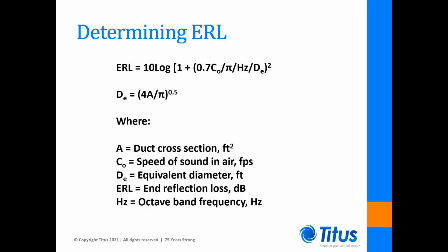These were to be added to each reported octave band up to a maximum increase of 14 decibels. Units with smaller discharge dimensions saw the biggest increases, and larger units were hardly affected at all.